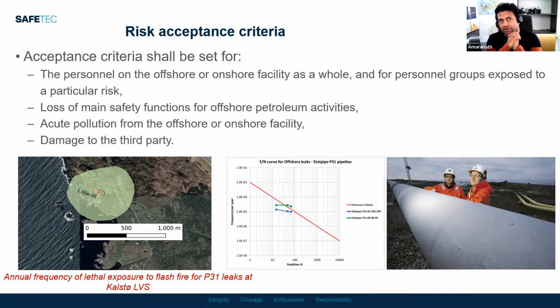But for offshore pipelines, you don't have requirements for the depth where the pipeline is located, but you have to take precautions to avoid free spans and the risk of pipeline damage due to trawling and anchoring.